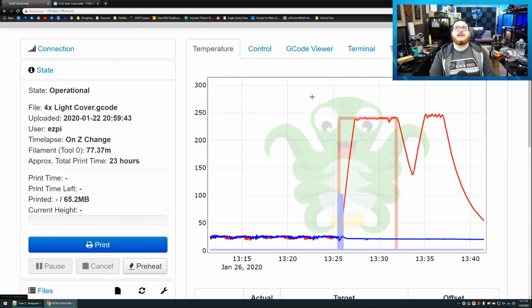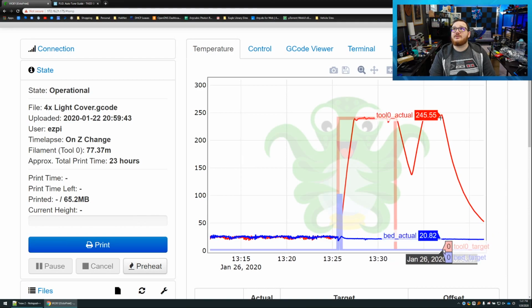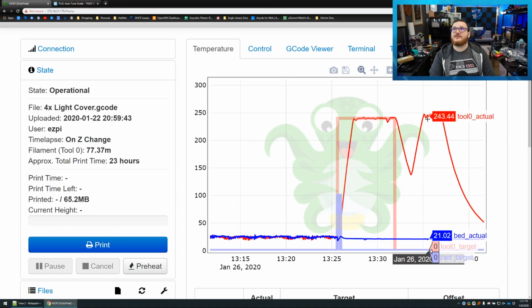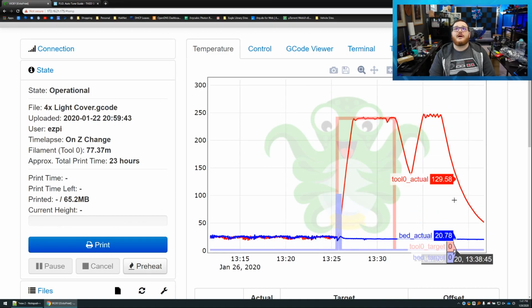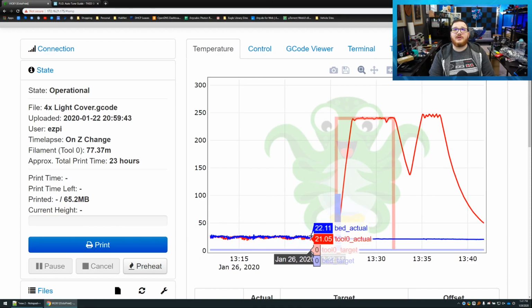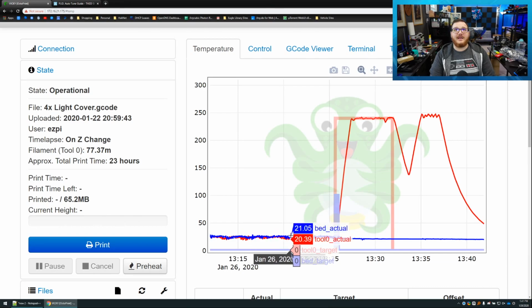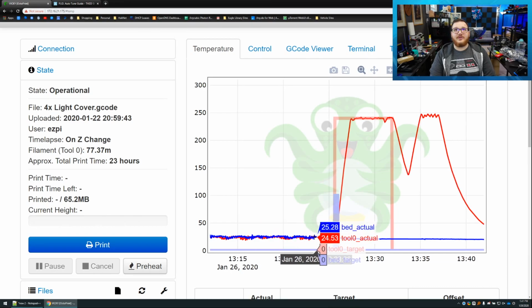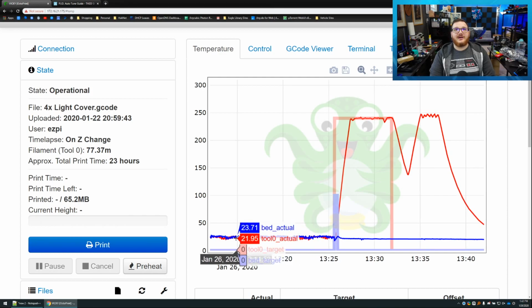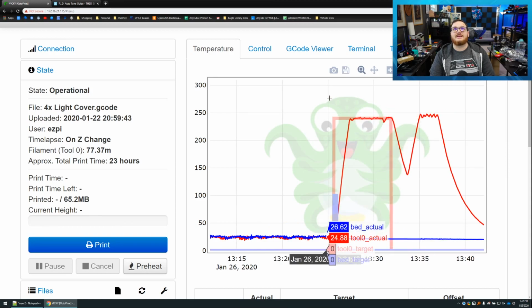Our temperature, you can see, has dropped off. And you can see here the cycling that's occurring as it does the PID tune, trying to get it more and more accurate. Basically, the goal is a flatter line. If you're wondering why this looks so weird, with these really weird values all over the place, it's because when it's in the ATX power off mode, the board is only getting power from the Pi, and it's not super stable. It's stable enough to run the board and keep it on, but the temperature readings fluctuate. But once you power on the machine, you can see it's dead on.